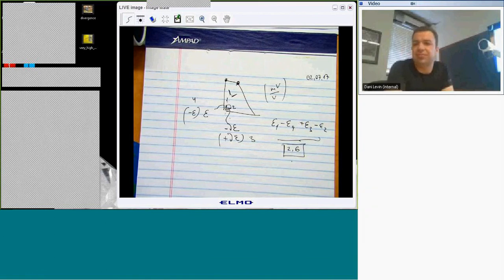If you look very closely, and you don't have too much noise in the system, you'll see little peaks at various frequencies that correspond to all of those resonant frequencies that you calculated. And of course, if your calculation is fairly accurate, then you can identify which mode you're at. Oh, I calculated it's going to be 4.6, I measured a mode at 4.5, that's probably that mode, right? Now, if it turns out your calculated frequencies are way off from your measured frequency, then clearly there's an issue. We hope not to get that.